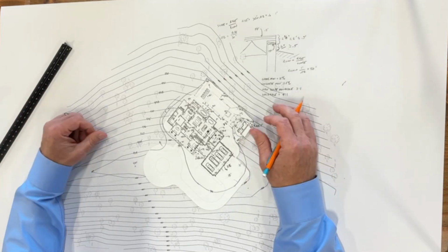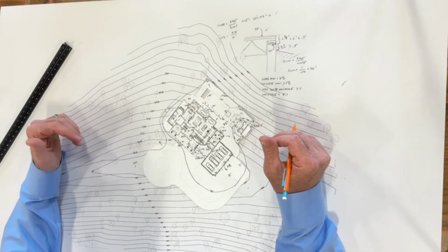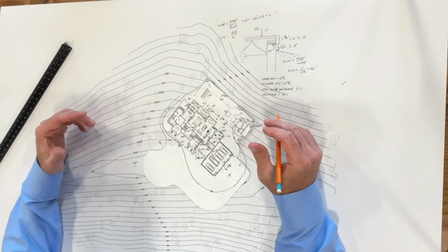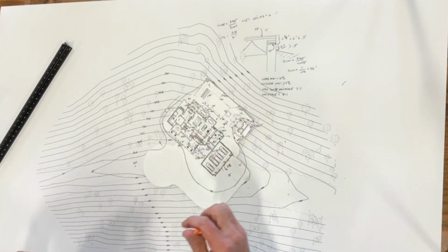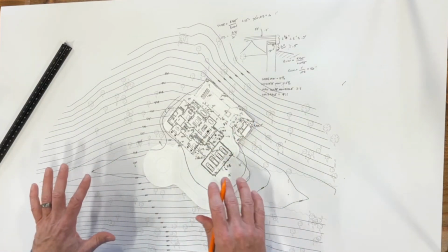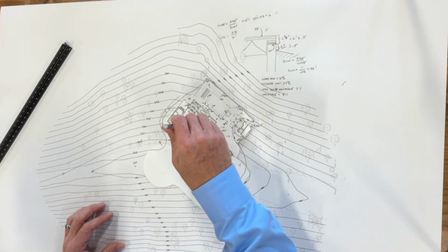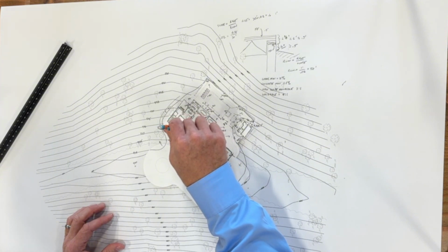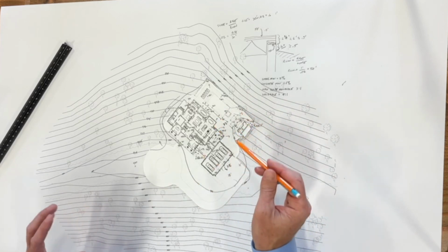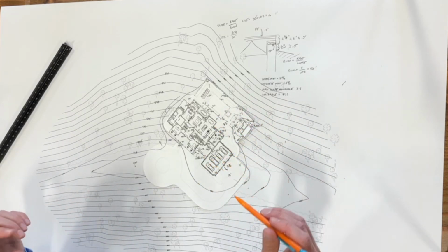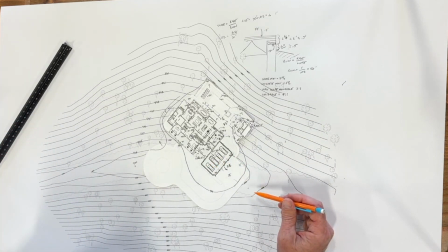By the way, does anybody know why these are like 900, this random dimension of 940 instead of like 100? It's from sea level. From sea level, right. So that's the sea level dimension. Now, what I've also seen a lot of people do is, because honestly it doesn't matter, you could just pick one and call it 100 and then just go up or down and it still would look the same. It's just this happens to be accurate with sea level, but you don't have to do it that way. Or sometimes people say the top of the foundation is 100 and then you work from the top of the foundation, which is kind of handy because then you could look at everything in relation to the top of foundation. Or even better is you go to the bottom of footing because that's where they actually dig the hole.